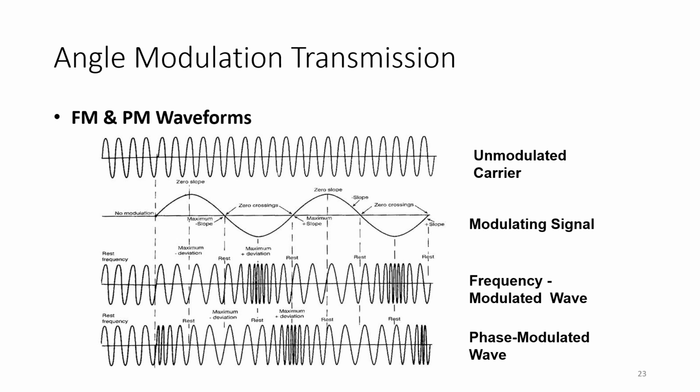So what do we mean by that? For the highest and for the lowest peak, there you can see the lowest and the highest frequency deviation. When you are not at the highest or at its lower peak, you have the constant value. So the highest frequency change occurs at the peak of the modulating signal. For PM, as you can see, the frequency deviation is maximum at zero crossing. At zero crossing, like this one, it has a maximum. Another zero, it has the minimum. Another zero, it has the maximum. And when you have another zero, we have the minimum. So you can see the difference.